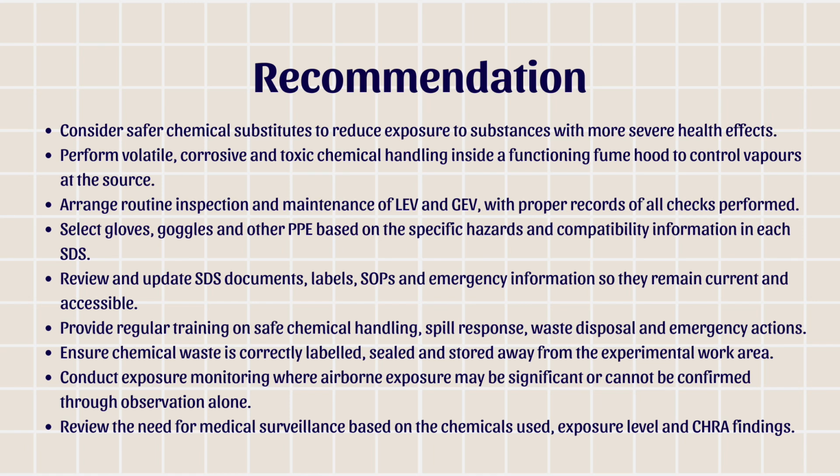Regular training should also be provided on safe chemical handling, spill response, waste disposal, and emergency procedures. Chemical waste must be correctly labeled, tightly sealed, and stored in the designated area away from experimental workstations.